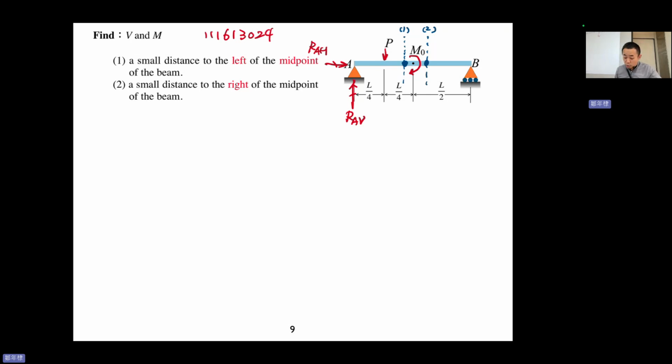Very nice. So we have two reaction force. Anyone want to grab another chance for B? RB to which direction? Vertical. Very nice. Any for horizontal? No. Good. RBV. No horizontal because it's a track.